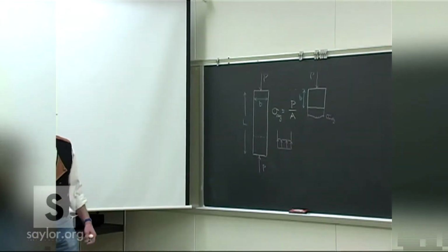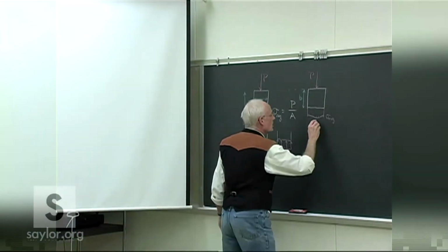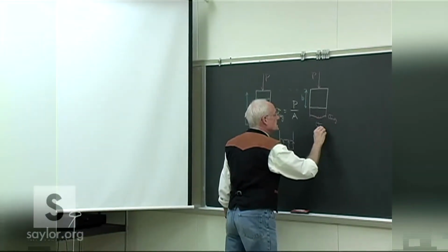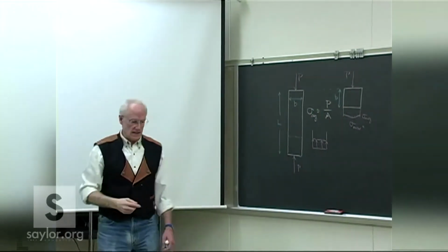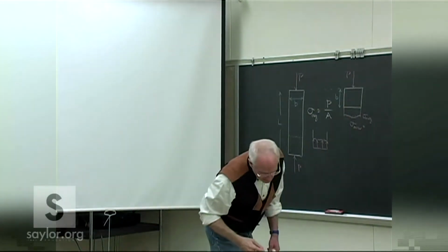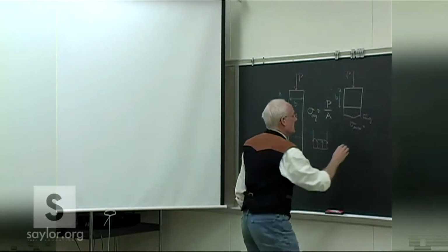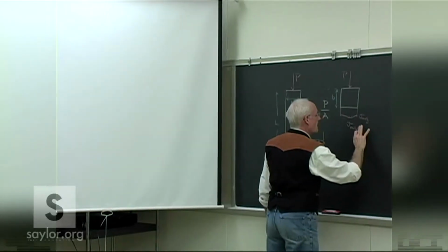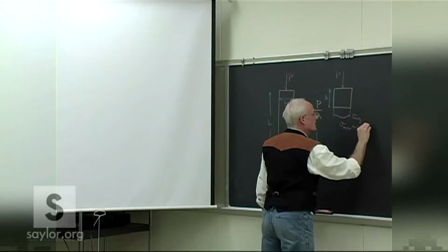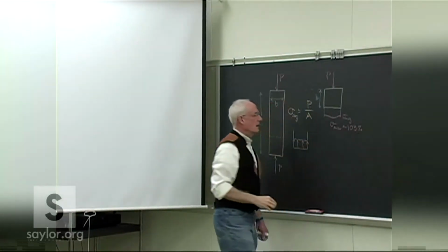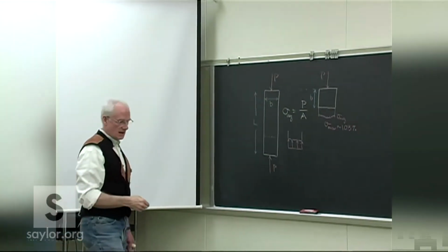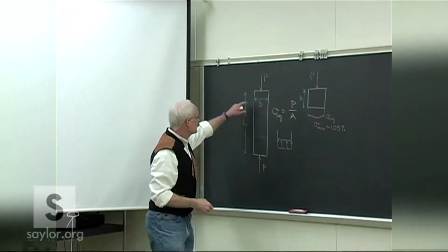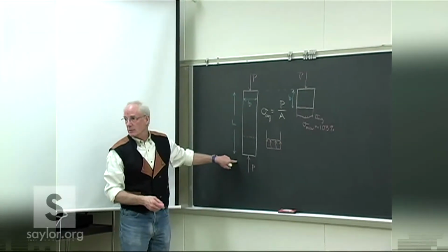There is a maximum stress somewhere about the middle of the piece. And again, remember, this is a point load I'm applying at the end. And that maximum load is about 103% of the average we have been using. So it's not a big error, especially if we're talking about very long pieces.